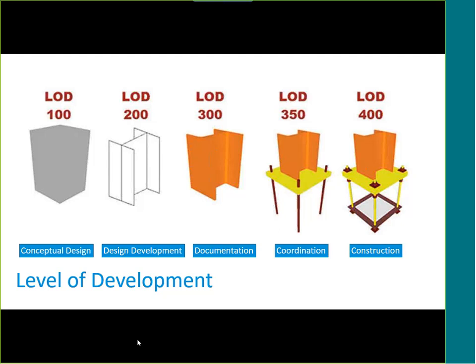The structural model includes welds, copings, washers, nuts, and all the assembly elements that you need to actually build it. There is an additional LOD 500, that's for facilities management, and that's where the BIM model is created with as-built information that supports the ongoing operations.